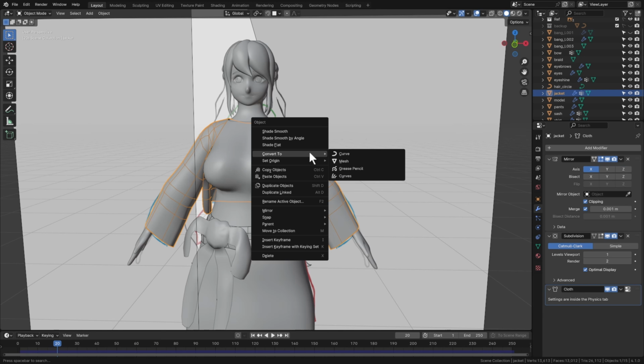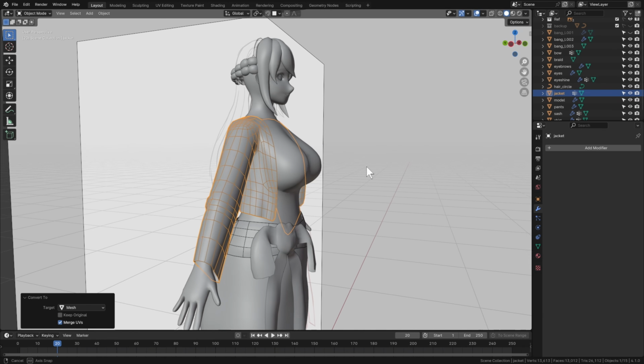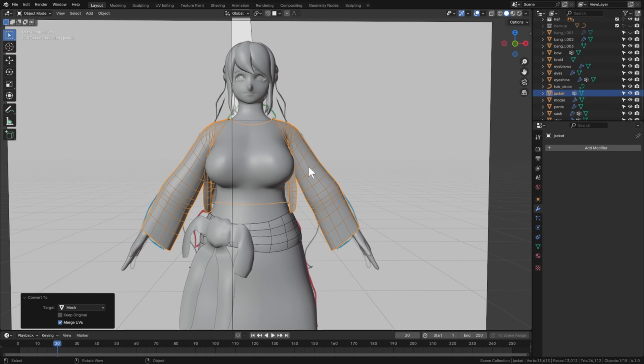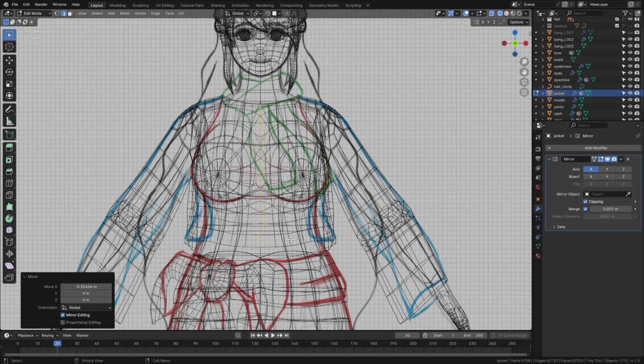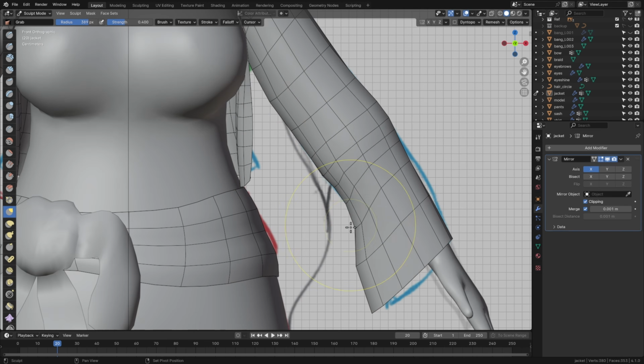It's more complicated to undo the subdivisions this time around due to the shoulder and elbow topology, but thankfully it's not necessary anymore. The whole model has a subdivision of 1 anyway, so it'll all work out the same in the end. You can still cut half of the jacket and reapply the mirror modifier though, since that'll help with making tweaks. Finish the jacket by adjusting the sleeves and buffing out the parts inside the mesh in sculpt mode.